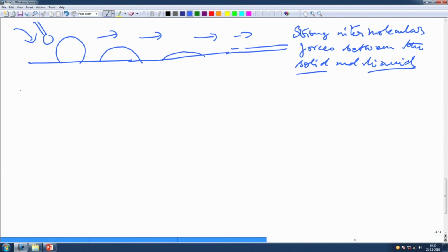So, that is the most important criterion, we will cover it in a little more detail later, but it is basically the nature of interaction between the substrate and the liquid. So, it is dependent on both the substrate as well as the liquid. They are like pairs. Okay. And that is what determines whether a droplet will sit nicely or it will spread. So, it is highly dependent on the surface properties, and as a result the intermolecular interactions between the solid and the liquid at the interface.